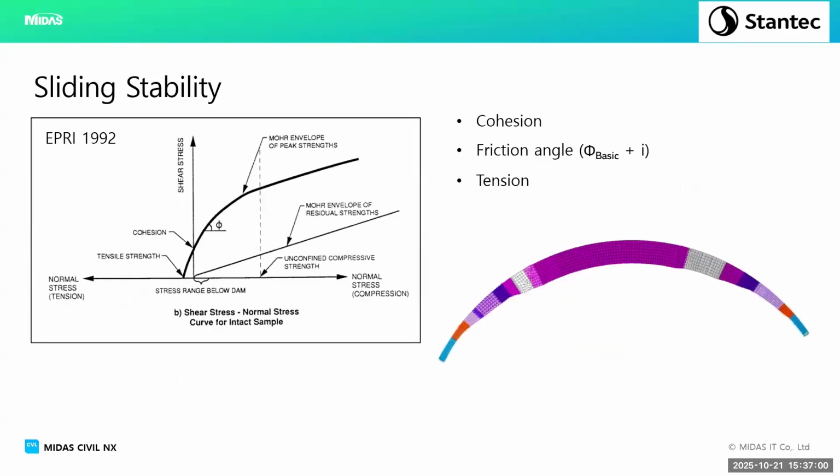So what's important, and I'm sure a lot of us have looked at this, is we've got the Mohr-Coulomb envelope. Now for rock or concrete, what have you, or in the interface, the actual curve of the Mohr-Coulomb is nonlinear. It's not a peak and a residual. Well, it's not linear. We want to understand at what pressures the structure is being exposed to. You can see there, depending on where it lies, your friction angle actually changes, your cohesion changes.